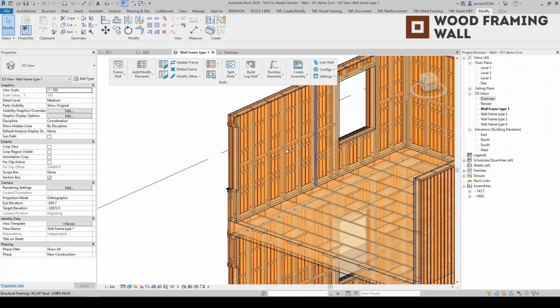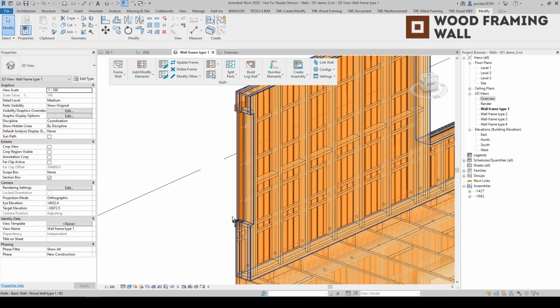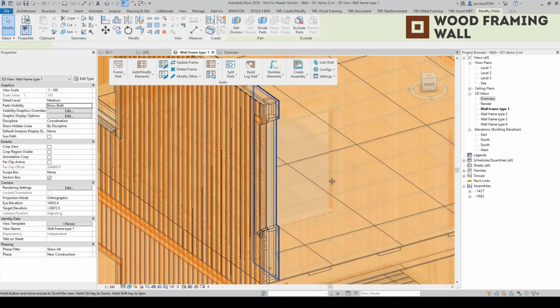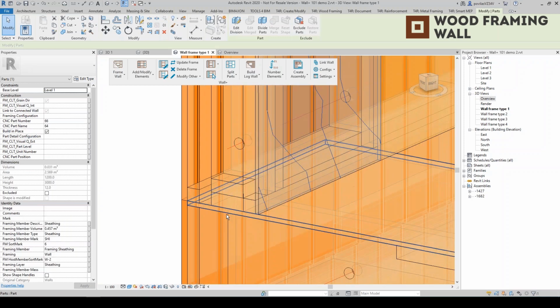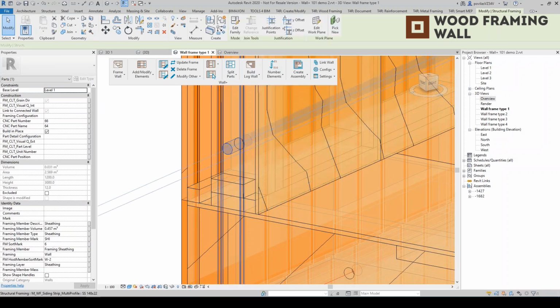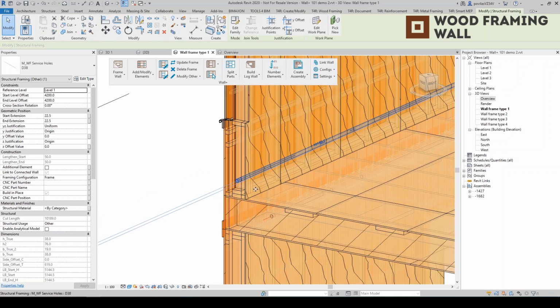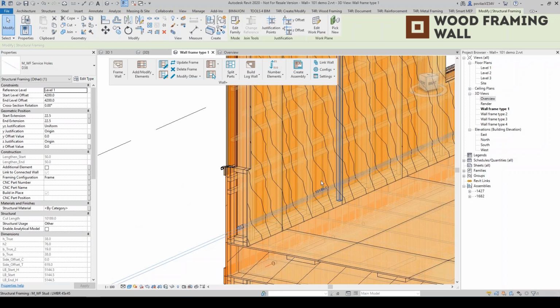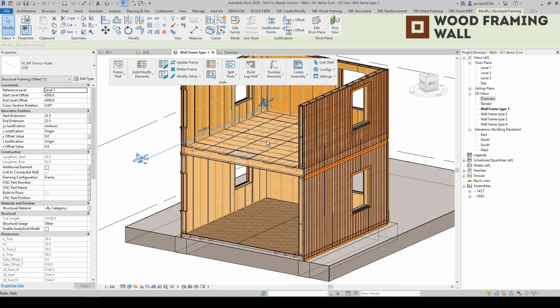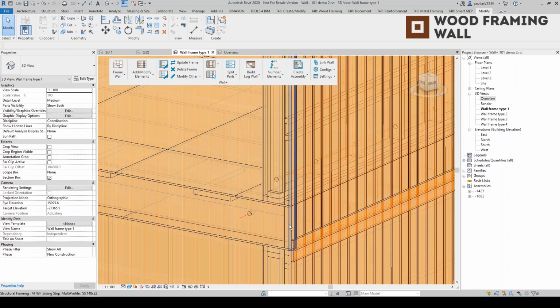Okay, I switch to both. I'm able to see all of my layers, including sheathing and structural framing. Okay, simple base plate, double plate, and service void, which we can have different diameter. We can spread it differently along the wall to fit our requirements.